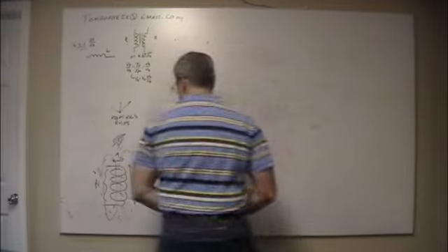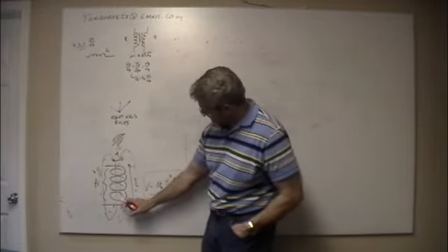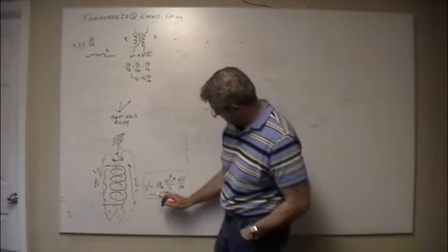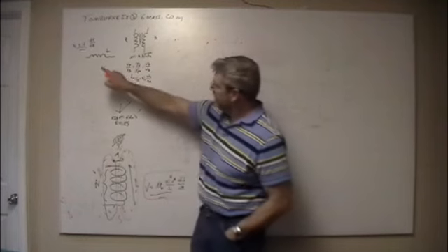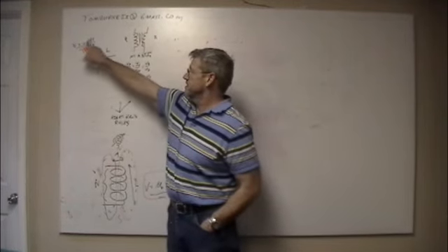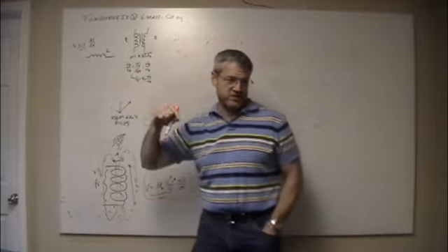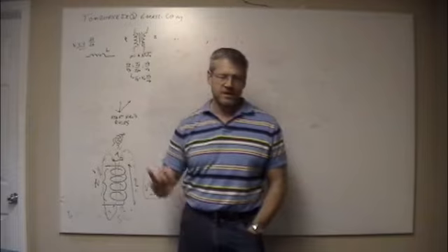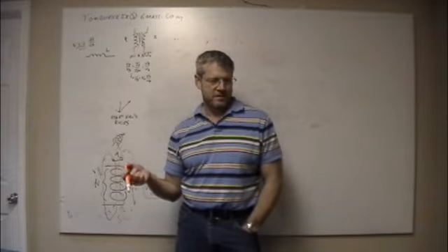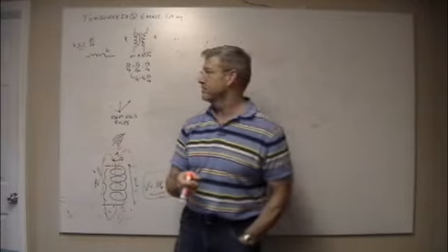Yeah. So now you start talking about, if you get down into the nasty, I talked about V is equal to the inductance times the change in current over the change in time. So a capacitor let high frequencies through, but it blocked low frequencies. An inductor does the opposite. It lets low frequencies through, but it doesn't like to let high frequencies through.